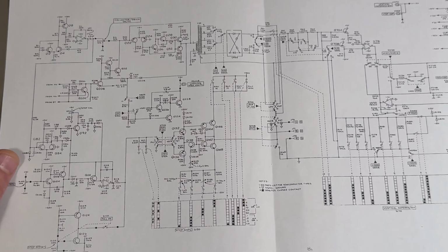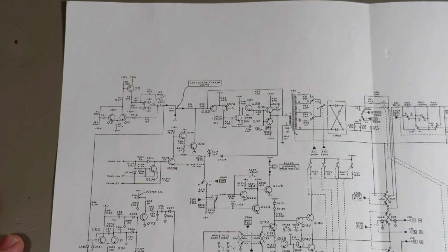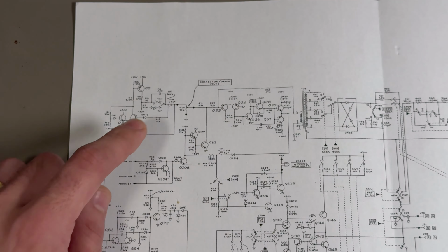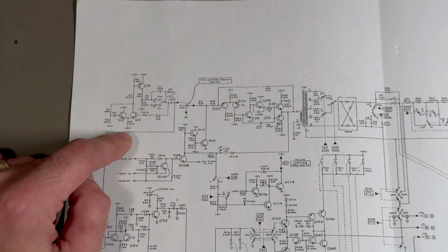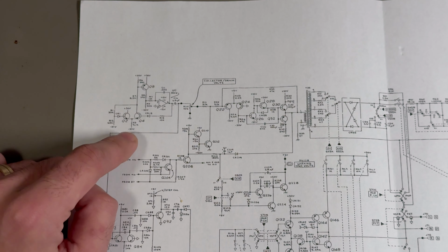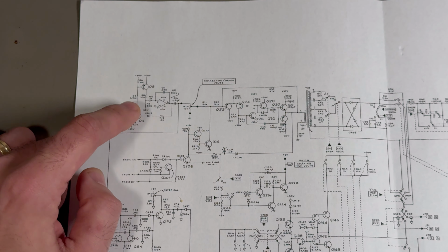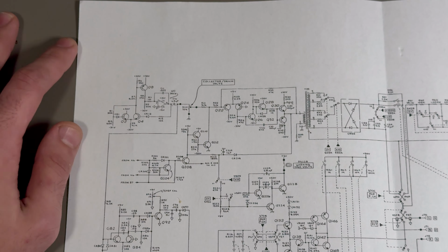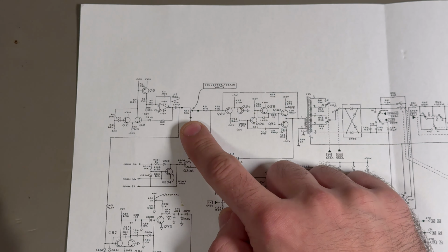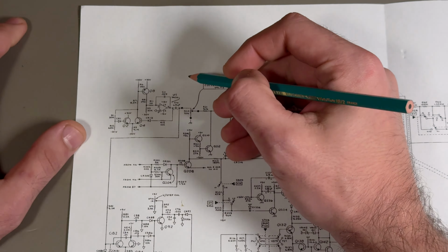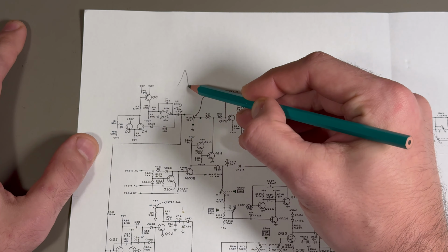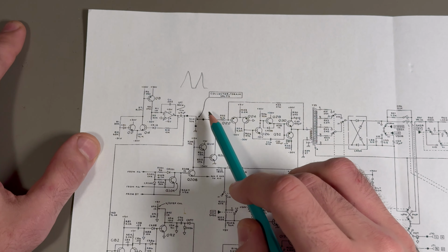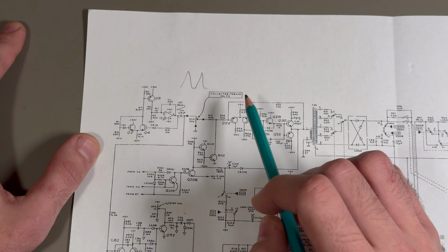So I'm just going to zoom in a bit here and take a look at the schematic and some of the building blocks. So this is a triangle wave oscillator. It's made out of an op-amp and a couple of transistors. This is a hysteresis comparator, so a comparator that has some hysteresis. And this point here will have a triangle wave that kind of looks like this with a tiny gap in between. And this is basically the start of the circuit.